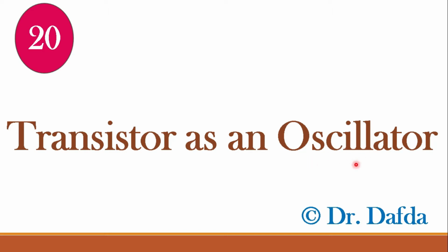And what is an oscillator? An oscillator in very simple terms is a waveform generator or a signal generator that generates waveforms at some particular frequency, right? More precisely, oscillators are circuits that generate a continuous voltage output waveform of constant amplitude at a required frequency. Now, how will this frequency be determined? This frequency will be determined by the capacitance, inductance or resistance that is used inside this oscillator circuit, right?